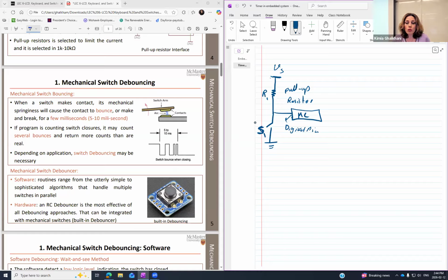And then we are going to have, on the other hand, the pull-down resistor. Suppose again you do have VS, the difference between pull-up and pull-down. Now the switch is connected to the voltage source. Instead of being connected to ground, now switch S1 is going to be directly connected to the voltage source. And then I'm going to look at the voltage between, now the microcontroller is still here, but if this one is open, I'm going to get rid of the voltage source.